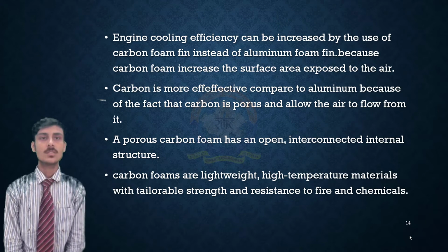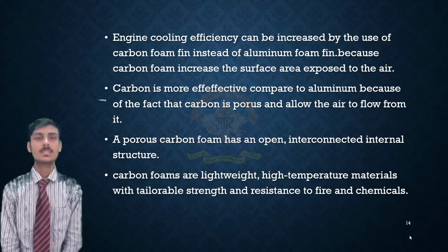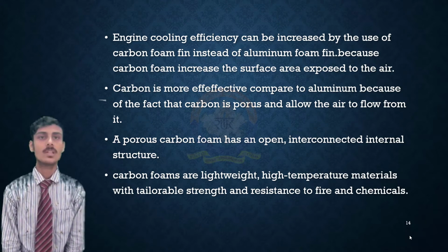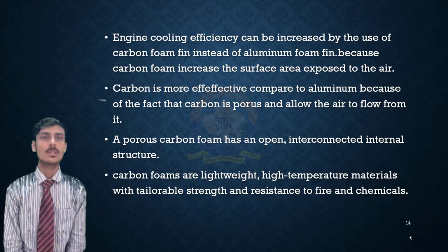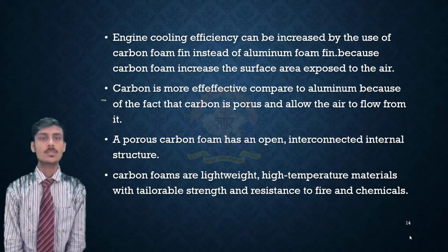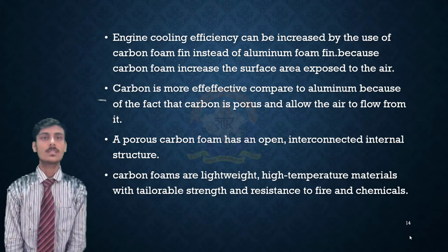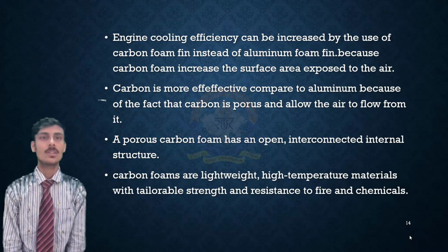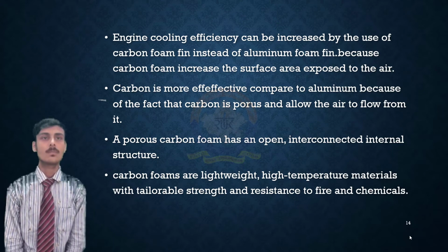Experiments suggest that engine cooling efficiency can be increased by the use of carbon foam fin instead of aluminum foam fin because carbon foam increases the surface area exposed to the air. Also, the porosity of carbon foam fin is higher compared to aluminum foam fin. That's why air can easily flow through the carbon.